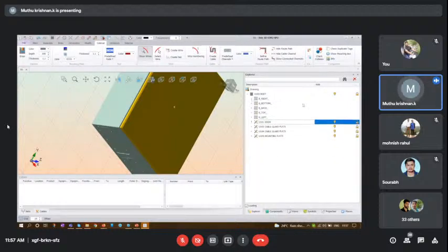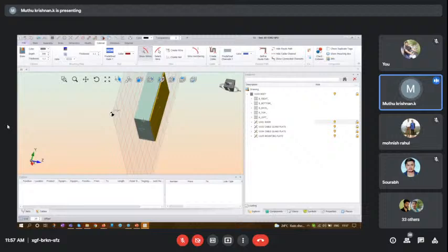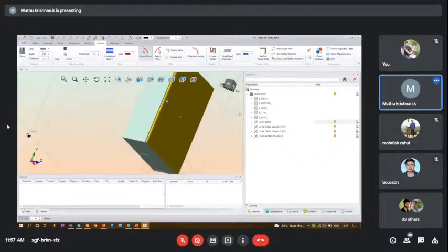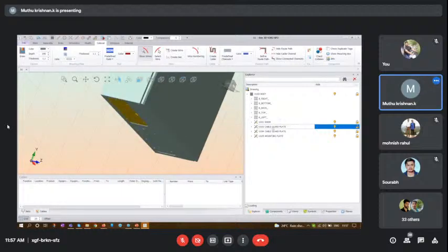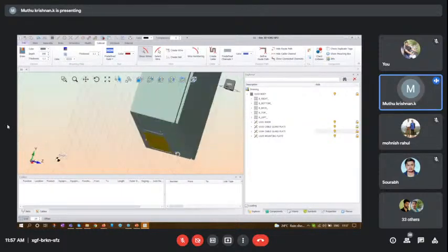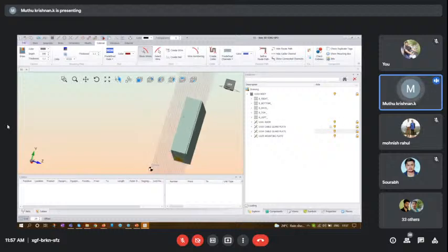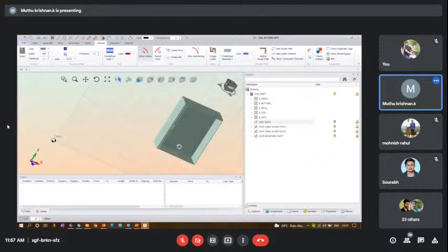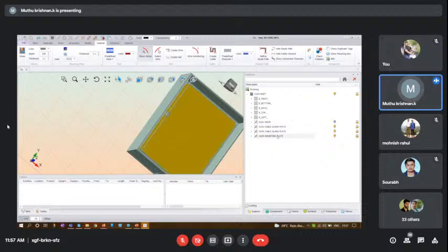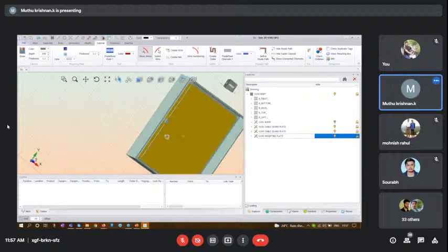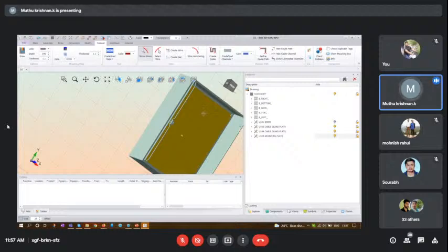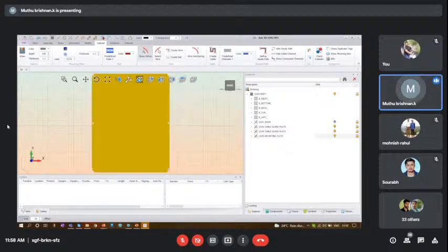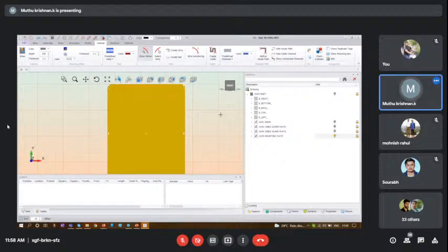So Explorer is kind of properties for the 3D object, where we can find panel doors, and we have a cable gland plate at the bottom, and second cable gland plate. And if I turn off the door, you can see a mounting plate inside the panel. So let us just work on the mounting plate for now. I turn off all the other entities apart from mounting plate.